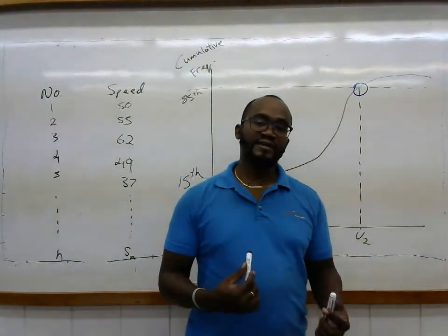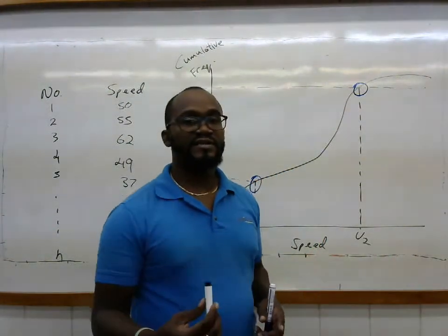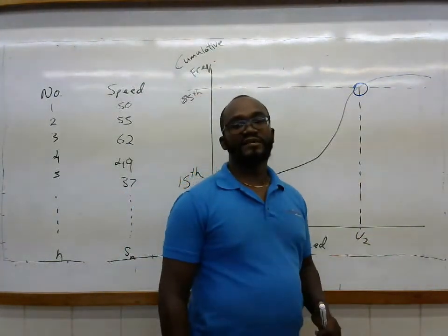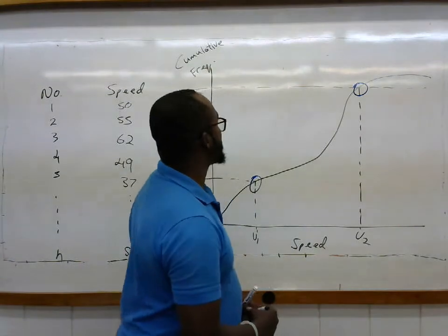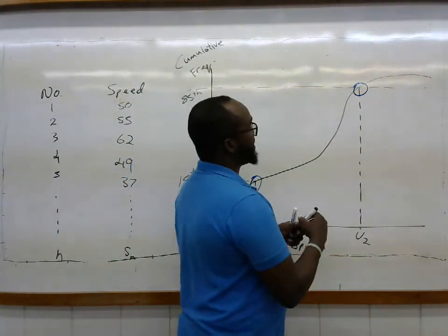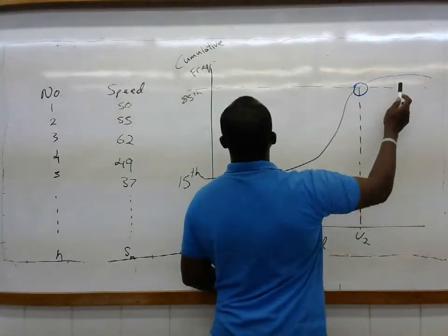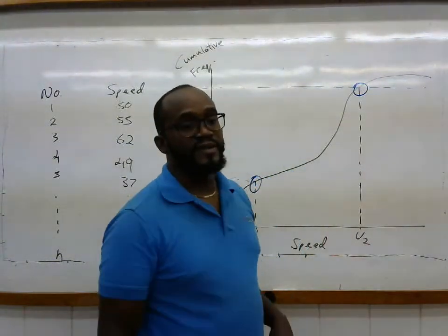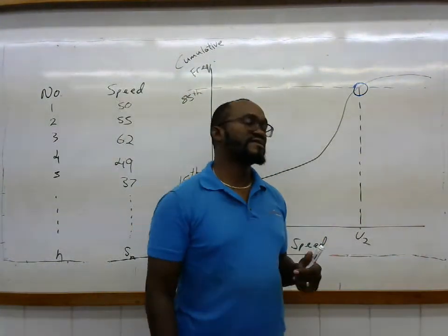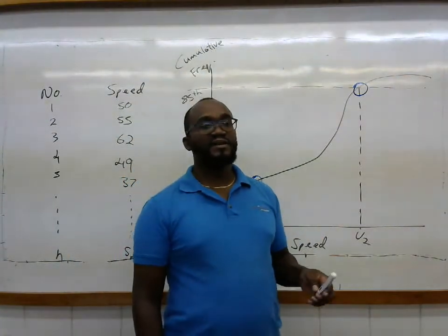So using that logic, engineers, practitioners, and policymakers have used that as a rule of thumb to set the posted speed limit. Okay, so the corollary to that is that anybody found to be over the 85th percentile speed would tend to be those who would be classed as riskier drivers, risk takers, careless, reckless as the case may be.